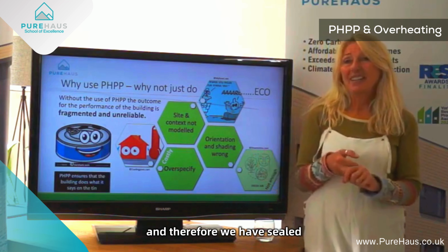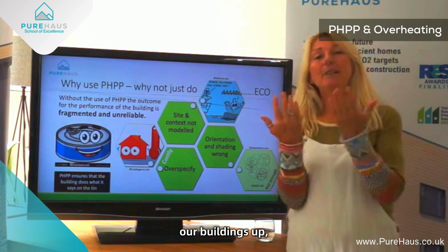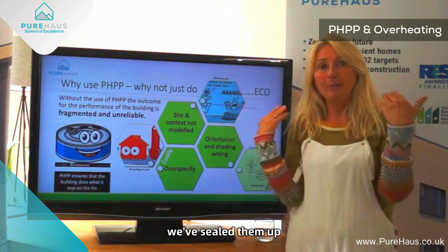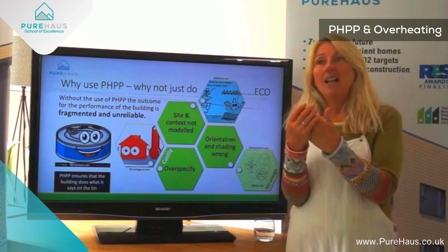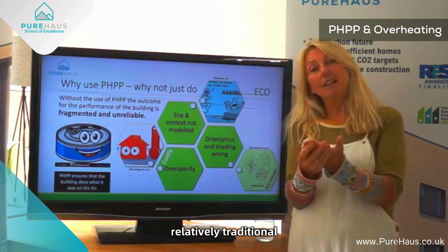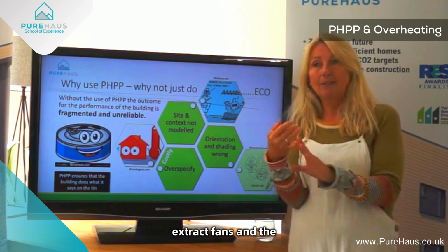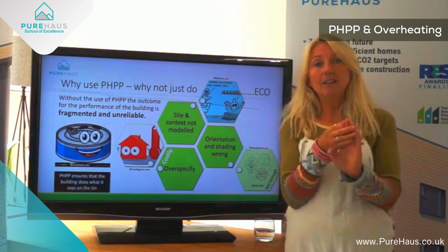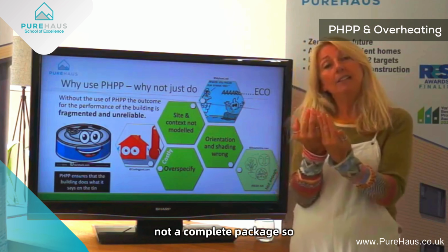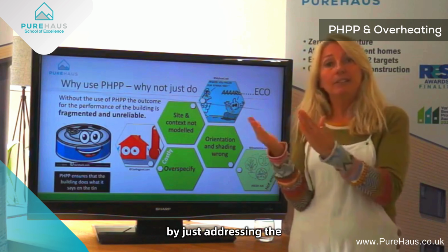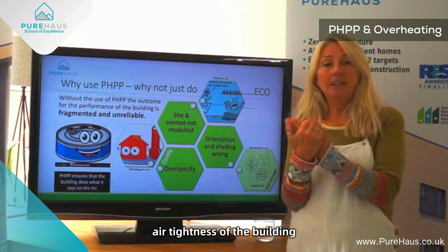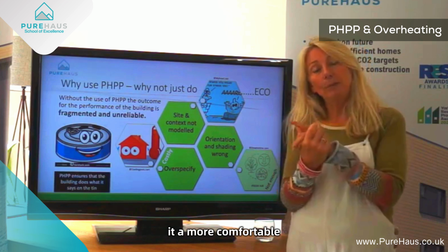And therefore, we have sealed our buildings up, made them warmer with better thermal insulation, and sealed them up with better airtightness, and we still rely on relatively traditional ventilation systems, extract fans and opening windows, etc. It's not holistic, it's not a complete package. So what we're finding is that by just addressing the insulation or just addressing the airtightness of the building, we're not actually making it a more comfortable place to live.